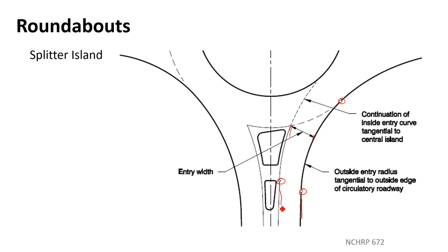This is probably more or less 12 feet back here. When we widen this out, this is 15 to 18, sometimes even more. We try not to make it so big that two cars can get side by side, because that confuses people, right? So at 18 to 20 feet, people probably aren't going to try to pass. If you get any bigger than that, they probably will. So for a single lane roundabout, that's what we would normally be looking at through there.